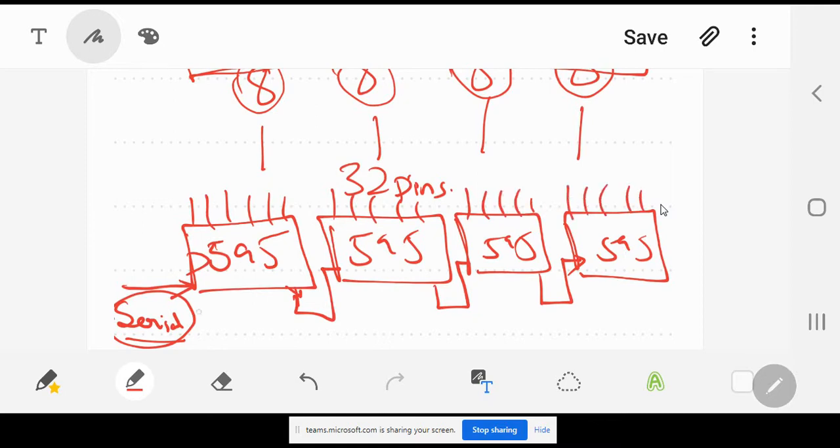So in this way, just by the use of one serial pin from the microcontroller and some clock over here and some associated pins which Sir Bilal will actually deal with you, you are going to have this 595 IC controlled from one pin of the microcontroller. You are going to have just 74HC595 giving you 8 bits. Now this is used where you want to convert 8-bit parallel data into serial.